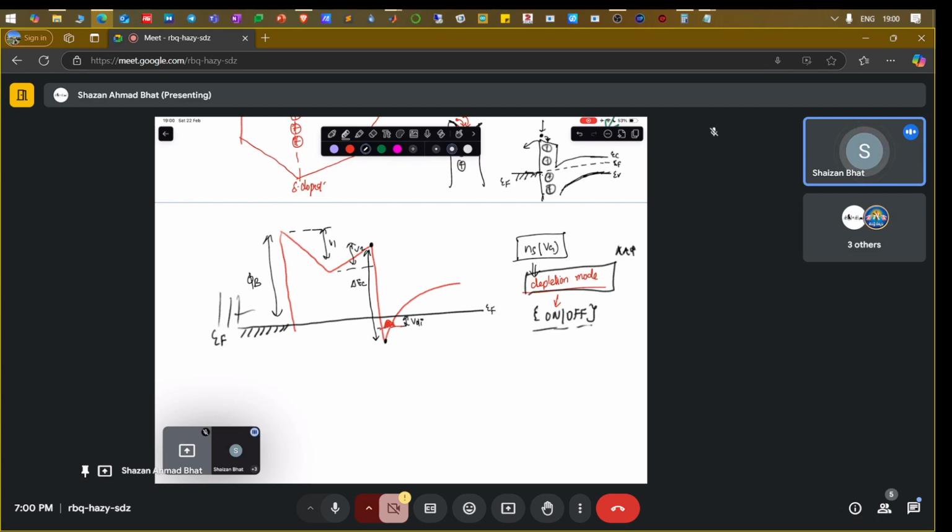In normal MOSFET devices, which are mostly enhancement mode, you don't have the channel, you create it by using the gate. But here it's the opposite scenario. So that's why the threshold voltage is negative here. You might have seen this in MESFETs also in the previous lectures, I think in week 3 or week 4. So that's why it's necessary for us to compute what happens to the sheet charge as a function of gate voltage.